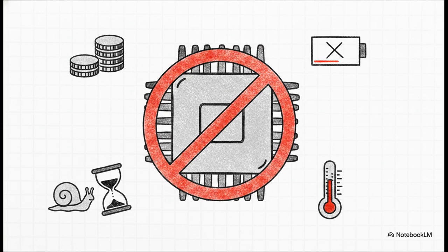Well, silicon area literally equates to manufacturing cost. And when you're manufacturing, say, 1 million microwaves, saving 50 cents on a microchip by dropping that FPU is a massive deal. Plus, power consumption drains batteries in portable devices, and latency just completely slows down real-time processing.